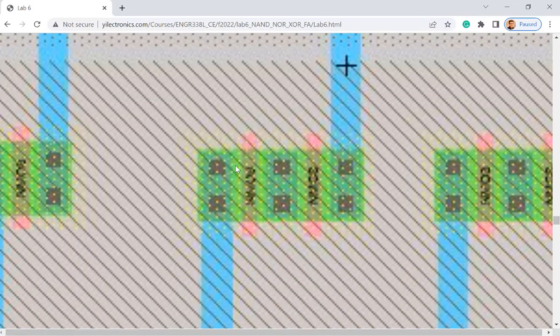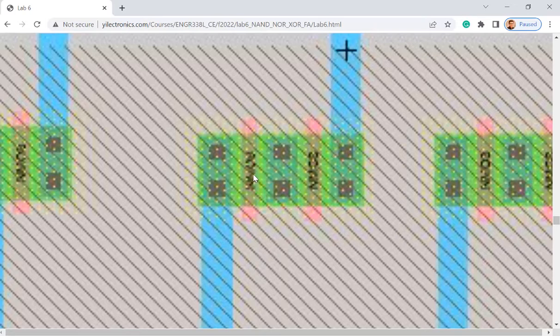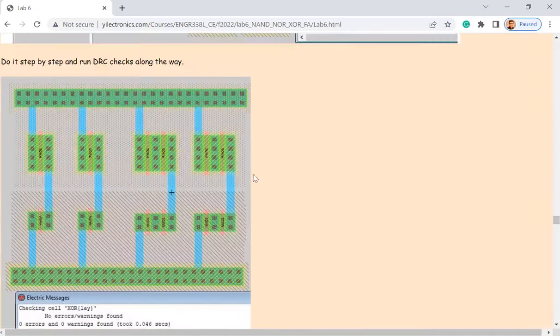And if you zoom in, you can see, are these NMOSes or PMOSes? NMOSes. Do you see the dots? It's the dots, right? So dots means these are N-type diffusion. And I can see that the dots are something like N plus or N wells. Slashes are either P plus or P sub. Okay. Same here. If you want to avoid all the well errors, just directly cover everything with the P sub layer.